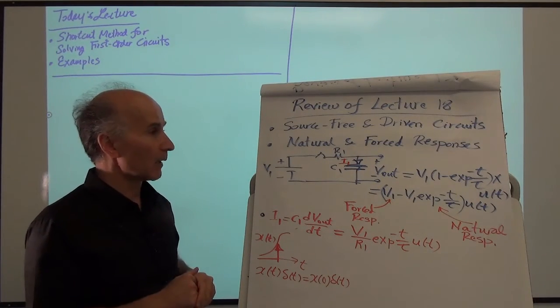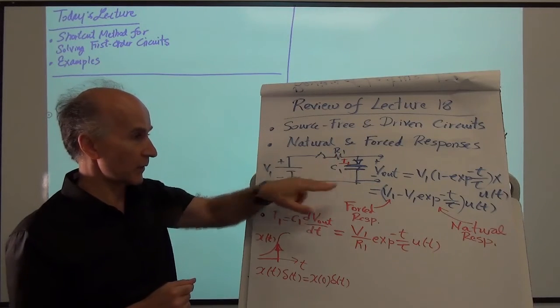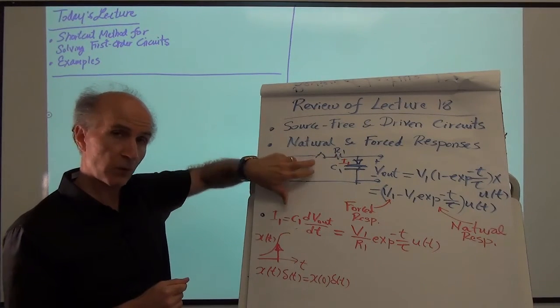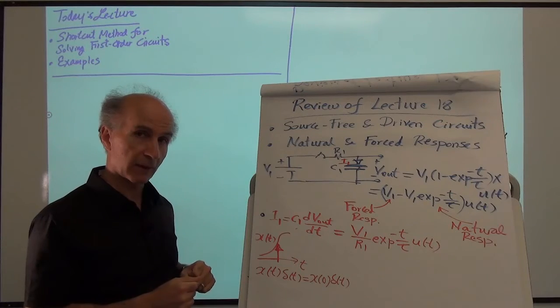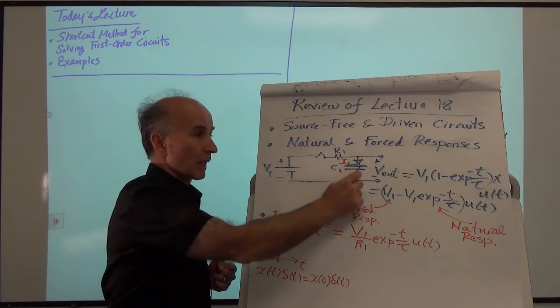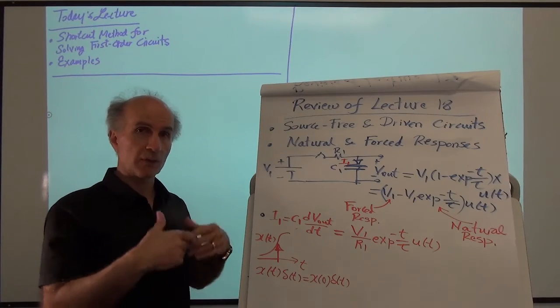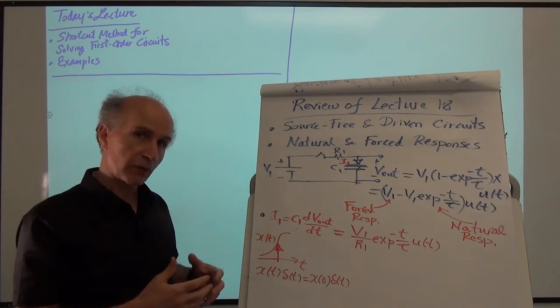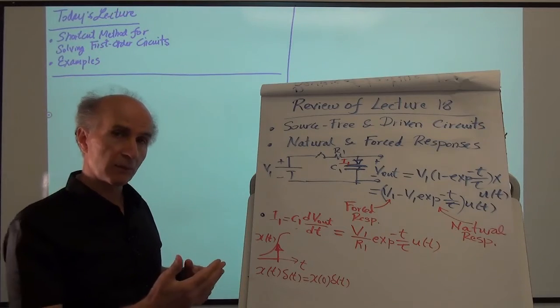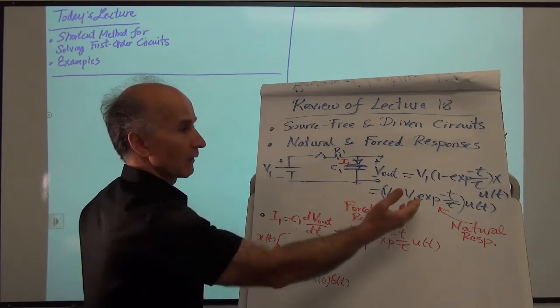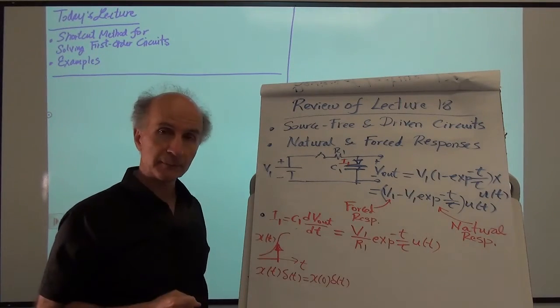So, for example, when we took this RC circuit and applied this voltage through a switch, we saw that suddenly we begin to establish a current through the branch, and that current wants to charge the capacitor. So the voltage on the capacitor rises with time and is given by these two equations.